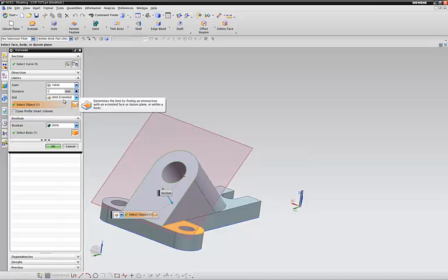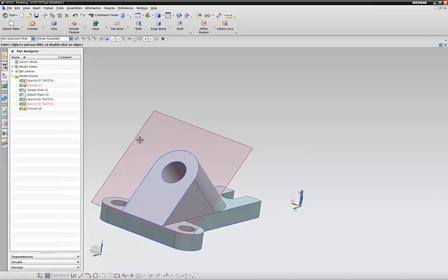We wanted to extend to a particular body. We located it to this location right here. And then we wanted to unite with that object. Or depending on other circumstances, you want it to subtract or do other things, or none of them. But we wanted to unite, which generated this surface right here.